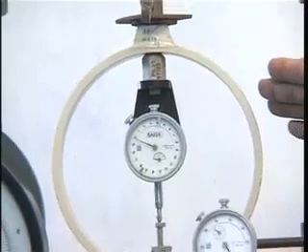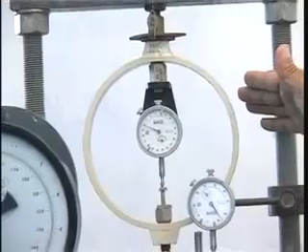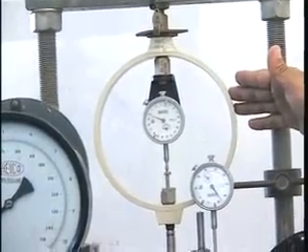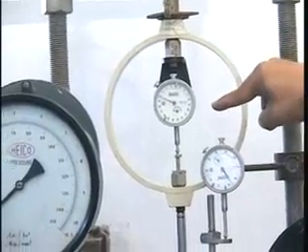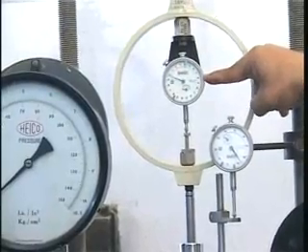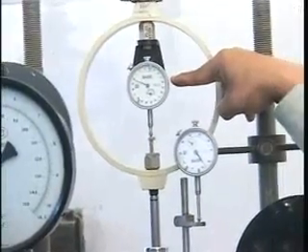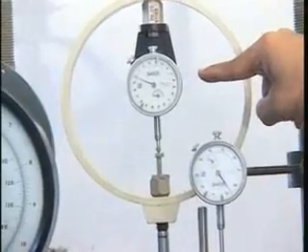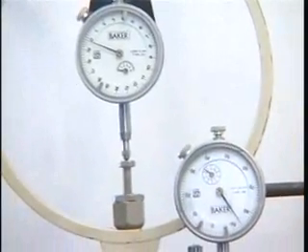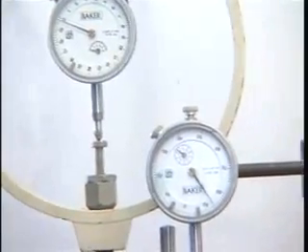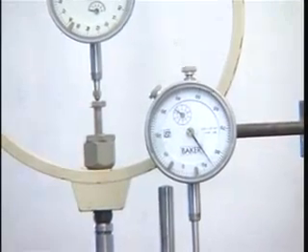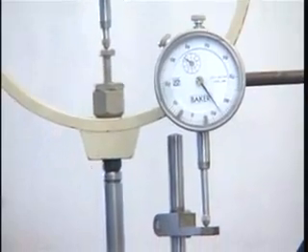Now we need to measure the axial stress on the triaxial sample, for which we make use of a proving ring here, and that is calibrated in such a manner that from the reading on this particular dial gauge we can find out what is the axial stress on the triaxial sample. Then we have got the displacement. We make use of this particular dial gauge for finding out what is the actual displacement of this particular triaxial setup,